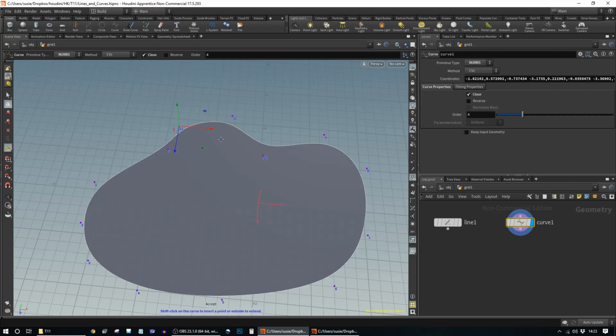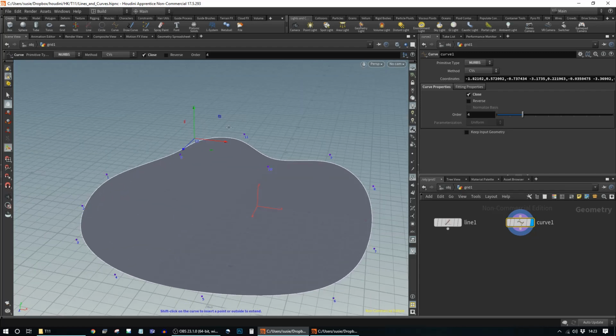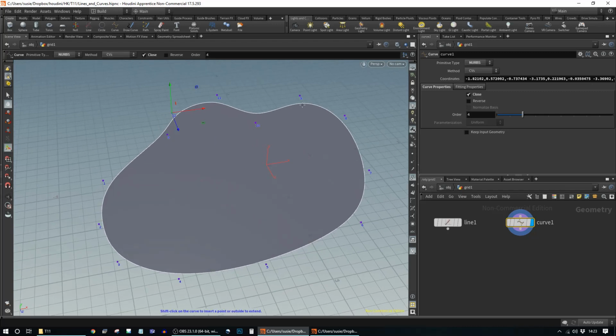There we go. So a control click onto the first point will join it up and turn it into a complete surface. Once you've created the points, you can go back and move them around. This still works within the individual node, so as long as you're just working on one point, it won't create any edit nodes, so you can get exactly what you want.